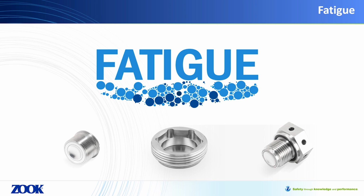Rupture discs are an excellent solution for pressure relief, but why do they fatigue? The reason is that they are a solid state device with no moving parts. As such, by design, they have no built-in safety margin. This is, at the same time, both a blessing and a curse, as the lack of safety margin is what ensures a rupture disc will always activate correctly. But it's also what gives the disc a limited service life.